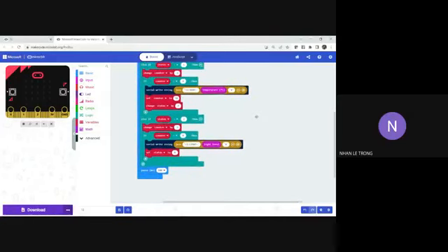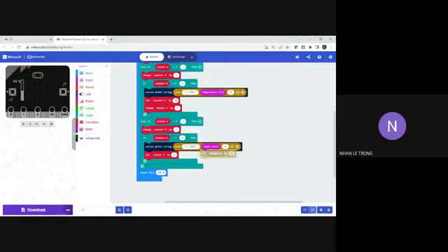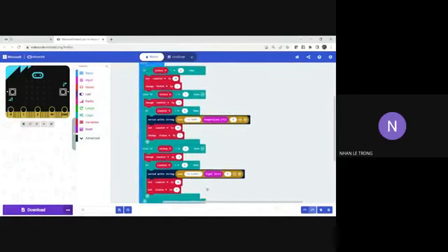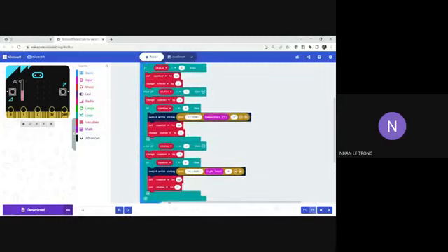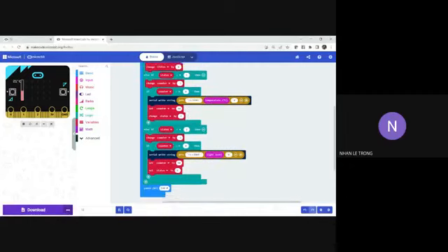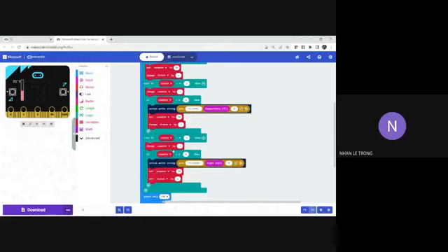Okay, there is an error. You need to set the counter to 50 before you move to step number 1 instead of step number 0. If you move to 0, it is also okay, but it goes to 1 immediately. So it is also okay if you set it to 0 here, but it is better to set it to 1. Because you send the temperature, wait 5 seconds, you send the light, and after 5 seconds you send the temperature again. So you switch between 1 and 2.